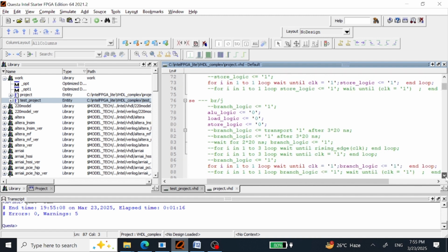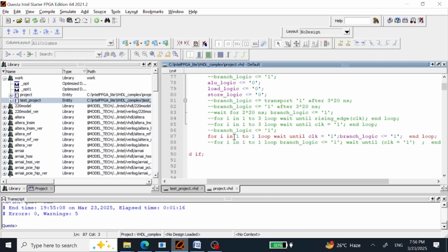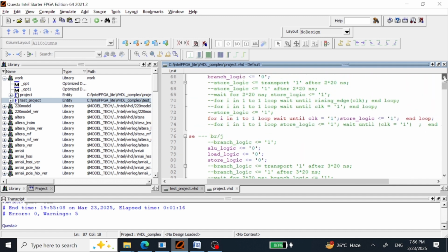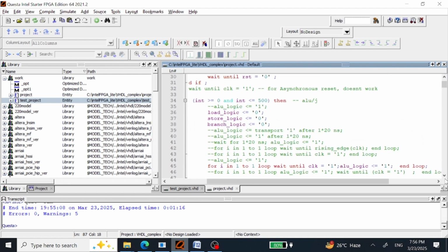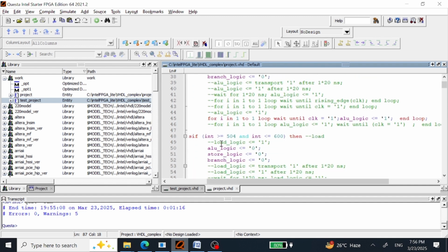And in the same way in the case of the 4th clock cycle, we are running this loop for only 1 clock cycle. But even if we make it 1 to 5 for 5 clock cycles, you guys are going to see the same output. The signal is going to only go up to 2 clock cycles. So this is the way these delays behave in a weird manner. And now I am going to show you one last case for this VHDL as well, and that is using this for loop.